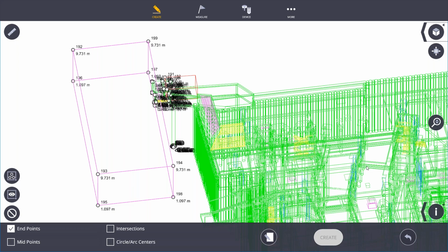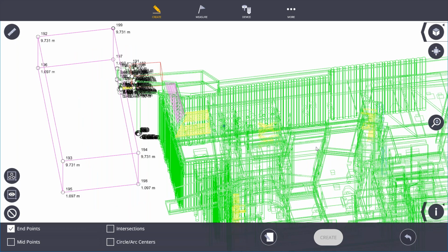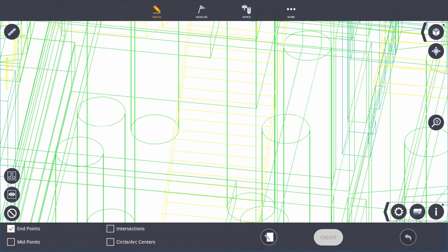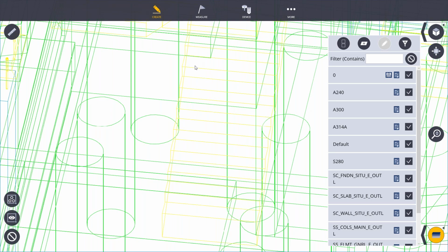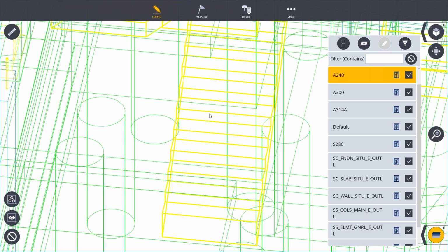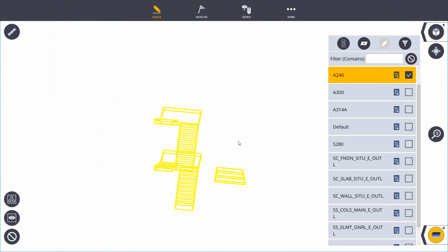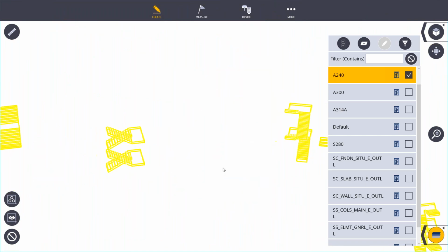Okay, so let's pick something out here within the design. Now I really like this because this is quite a big design. So what I can also do is turn on the layer manager. It gives me all the layers, but if I select this element here, it highlights that information and the layer that's relative to it. So I can jump about the design, picking out objects and shapes, or line work, and be working directly. If I turn everything else off, you can see that all I've got now are those objects within the design. So that's nice and quick and easy.